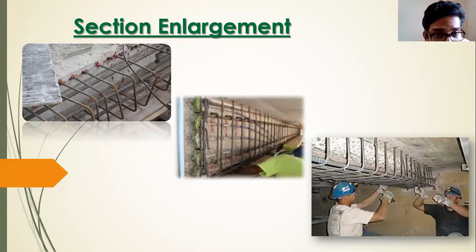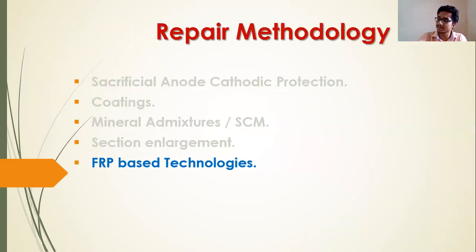Since you are enlarging the structure, the dead weight or self weight of the structure may also increase. So the design of everything should be able to take all those extra loads. A lot of hectic processes are there. Nowadays FRP based technologies are very, very important. In one case, the Pamban Bridge, they did some repair work using FRP technology. I'll show you some pictures as well of how it is done.